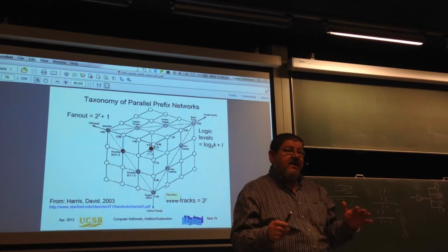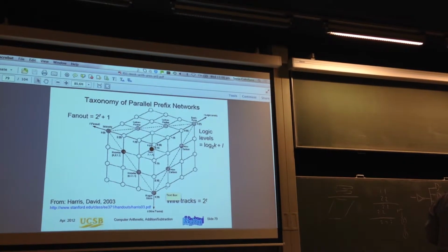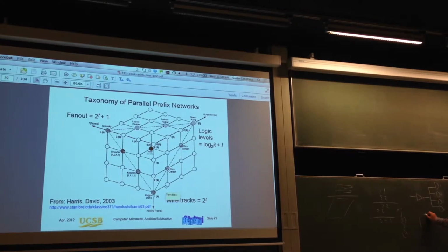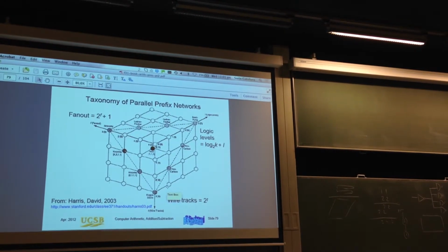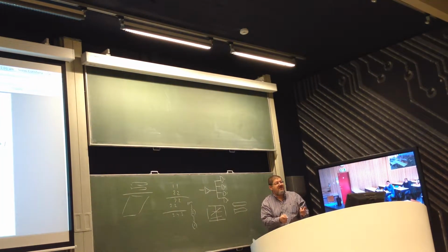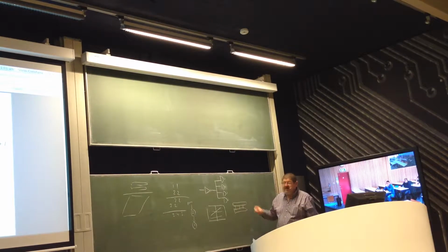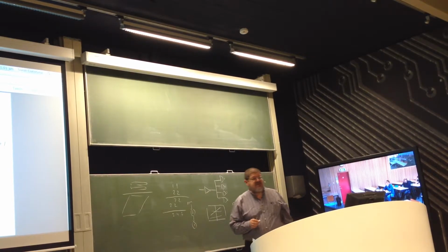But when you do that in silicon, there are advantages. One of the advantages of 3D technology is the following. I have a very large adder, because we talk about adders. Eventually, I have very long wires going on here. If I split it in half, and I fold it, and then I get 2 chips in this way, the longest wire will be half length. And I will have possibilities to connect those with what we call TSVs, through silicon vias.